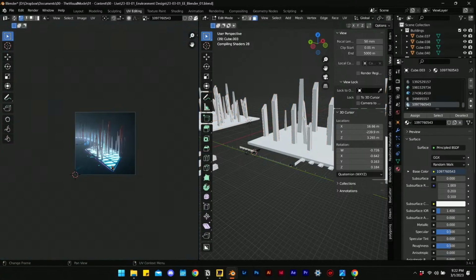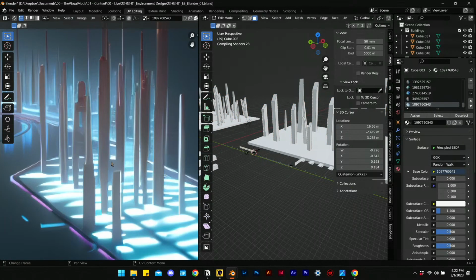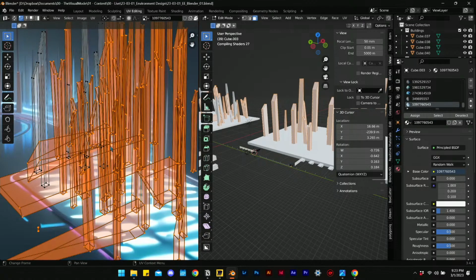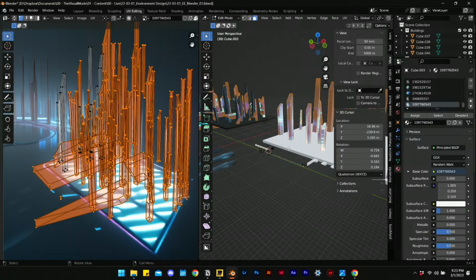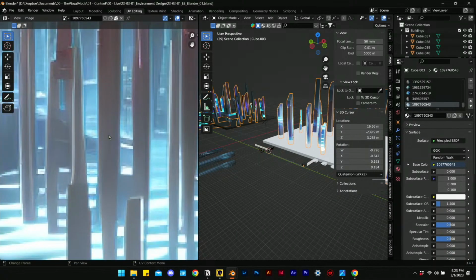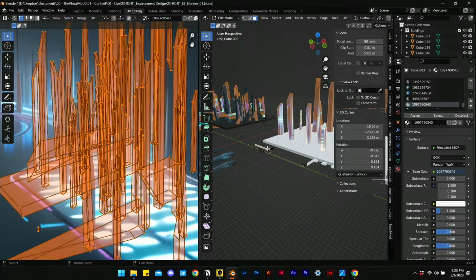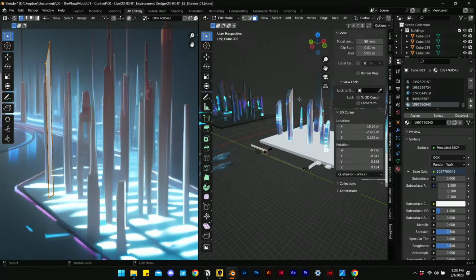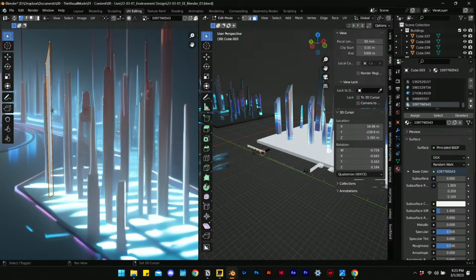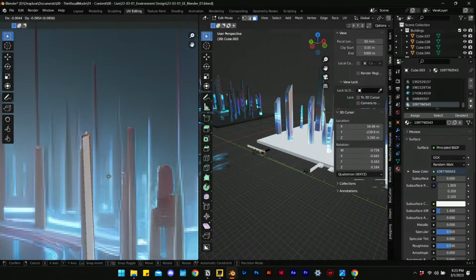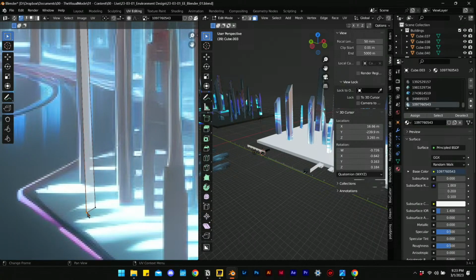we can actually see that all these buildings are actually being applied from this image. So the UVs are projected from a perspective to match onto this image. So any image, you can UV unwrap and edit all those points. If I were to just select one face of this building, like say this one, I get the four corners of that face of the building on the right, and I can see them here. And I'm going to actually retrofit that building to fit a shape a bit more accurately.